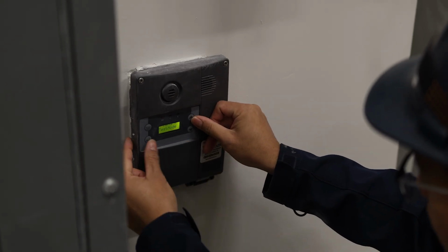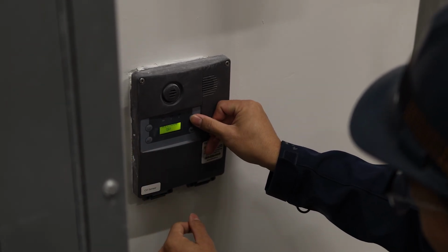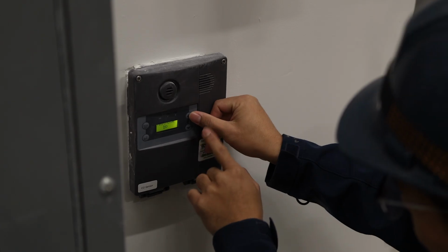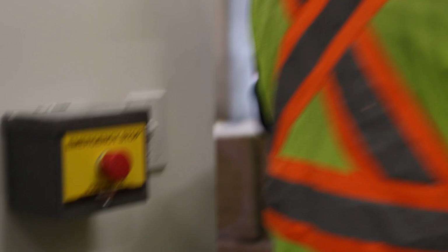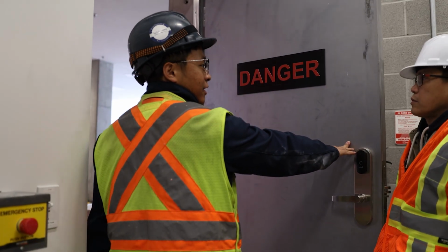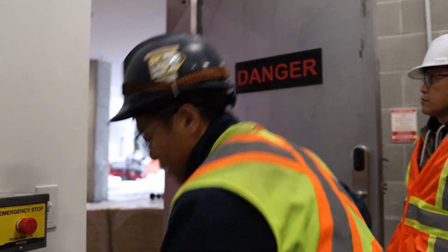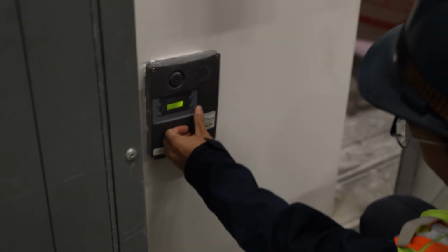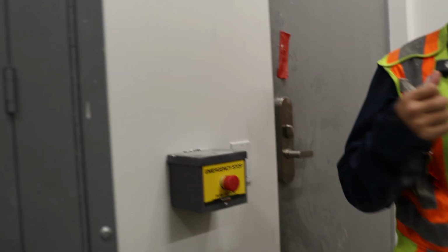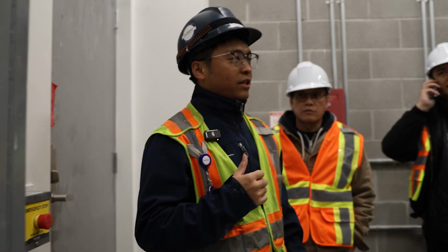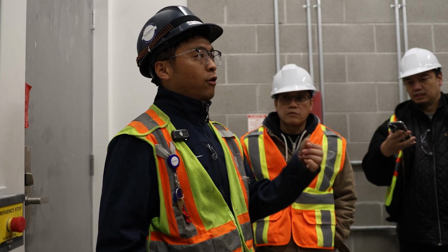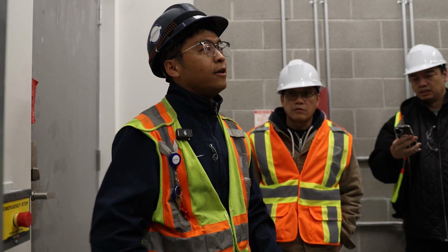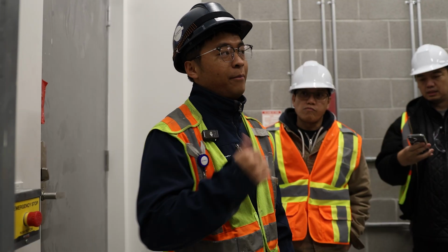Here is the test mode. If I click OK, test mode, now I press up, say yes. We should also hear that. That's for the second stage level. And then I can stop. There we go. That's what happens if the CO or NO2 level reaches the second stage. And it will also show the alarm in the BMS.